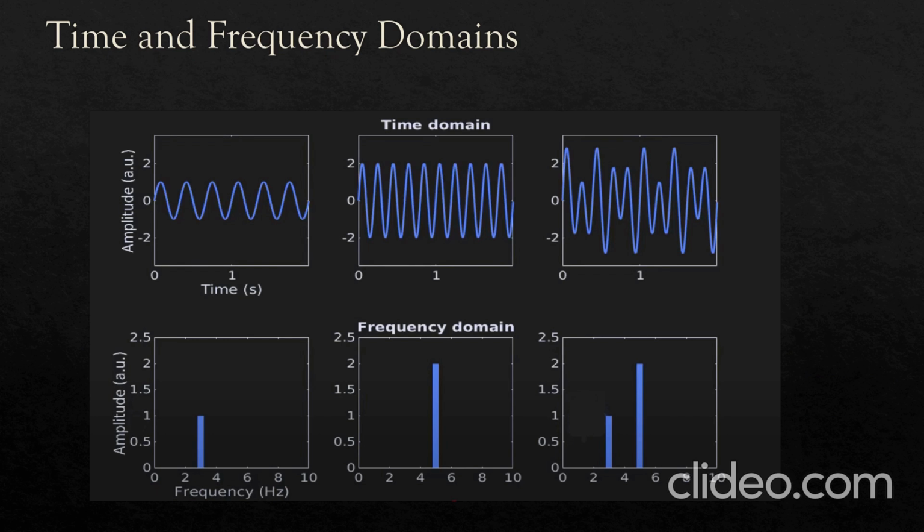The frequency domain represents a signal in terms of its frequency components, showing how much of a signal lies within each frequency band. We can obtain the frequency domain of a signal from the time domain by applying the Fourier transform. The salient feature of the frequency domain is that it reveals periodic components of a signal and is useful for identifying dominant oscillations or patterns. While the frequency domain is quite useful, it also doesn't show when specific frequencies occurred in time.